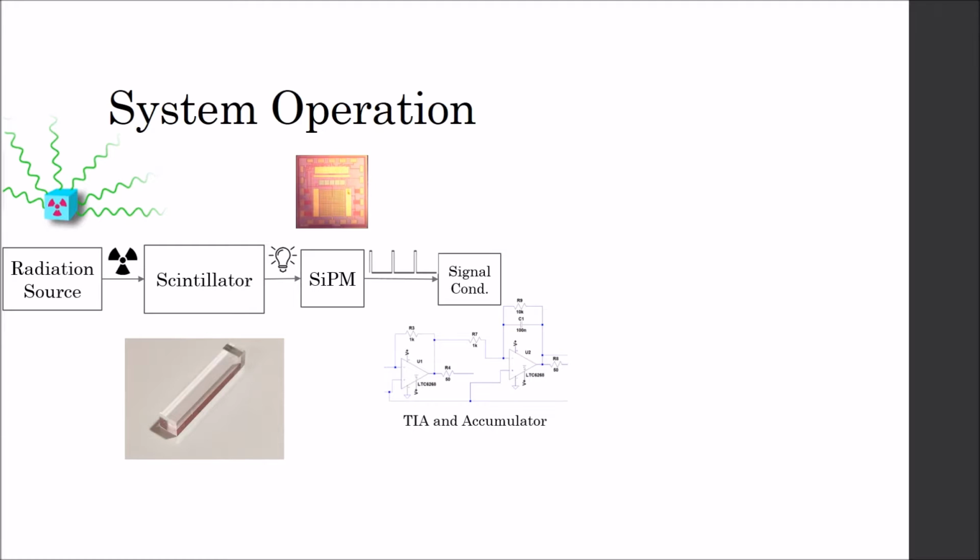The capacitor adds a memory element to the circuit, making it so the device isn't working at a full load every single time a breakdown incident occurs. Finally, the accumulator signal is sent into the rail-to-rail op-amps, which creates the differential outputs to drive the ADC. Differential outputs are immune to noise and are ideal for driving devices.